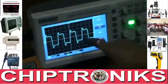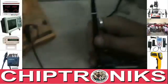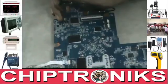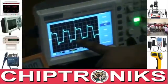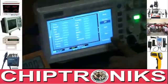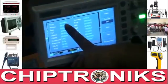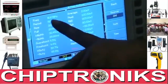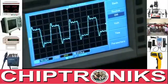Look, I'll show you. This is the BIOS IC. I'll check here 1, 2, 3, 4, 5, 6. Pin number 6, clock. Look at the signal, and I'll show you the frequency also. Look, 16.67 megahertz frequency. 16.67 megahertz. It will come from